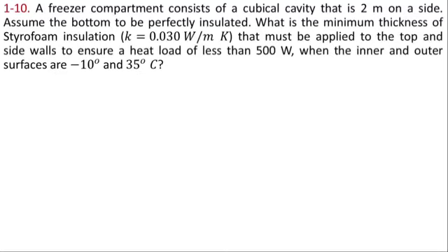In this statement, we have a freezer compartment, and the freezer compartment size is 2 meter by 2 meter. The freezer compartment is insulated by using styrofoam insulation, which has a thermal conductivity of 0.030 watt per meter Kelvin.